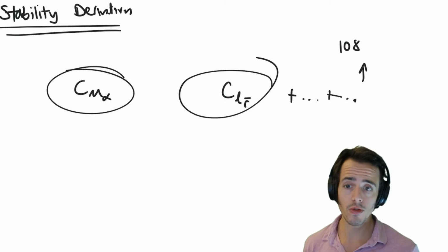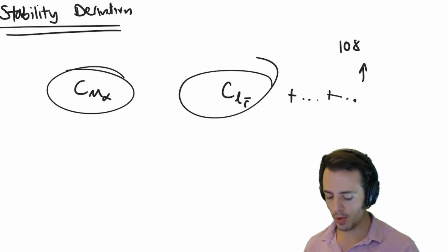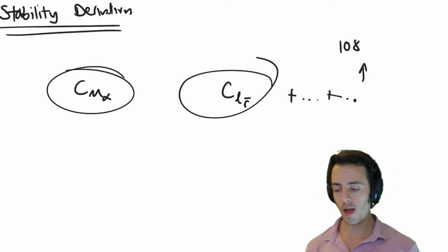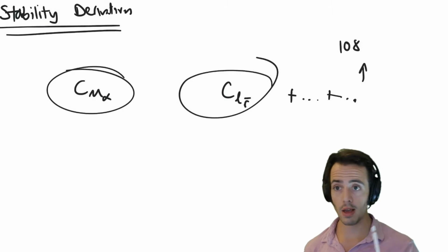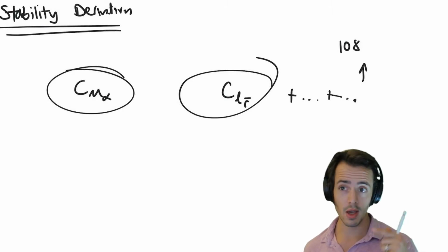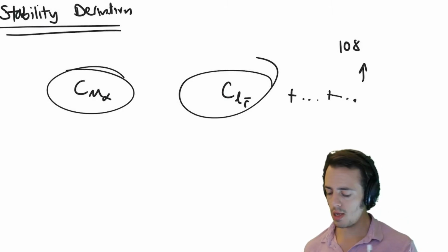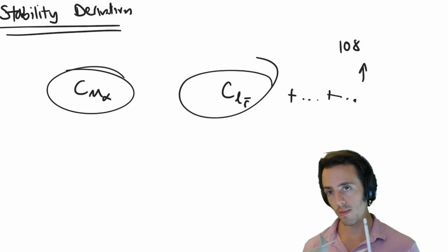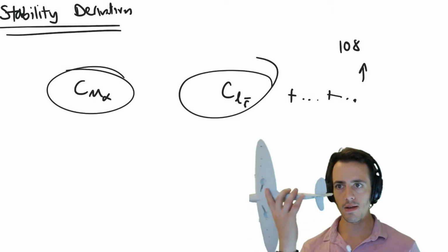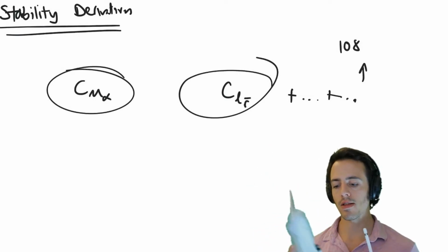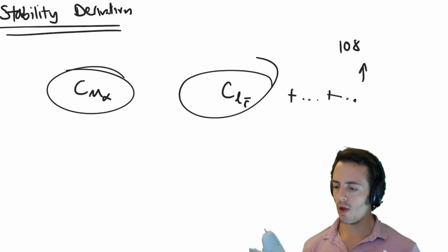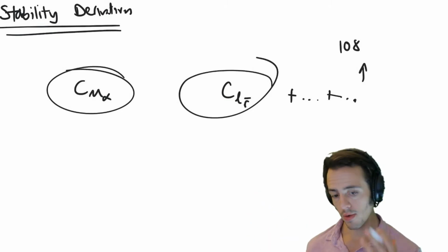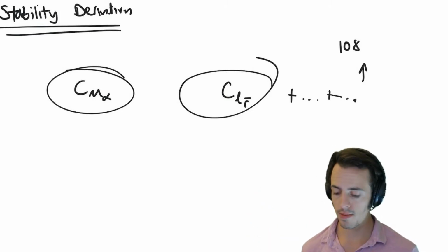We're constraining ourselves to the 6 aircraft degrees of freedom, so that's X, Y, and Z motion, and pitch, yaw, and roll. And then we're going to look at just the 3 main control surfaces: my ailerons, my elevator, I'm actually missing one half of my elevator, and the rudder. With those derivatives and those degrees of freedom, we end up with 108 stability derivatives.